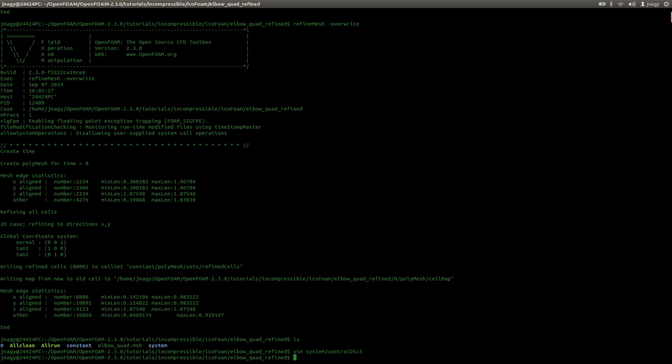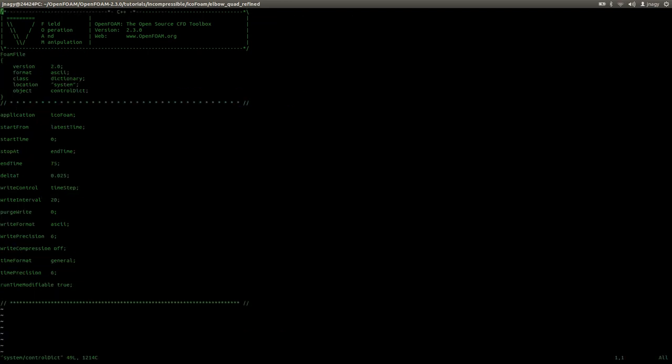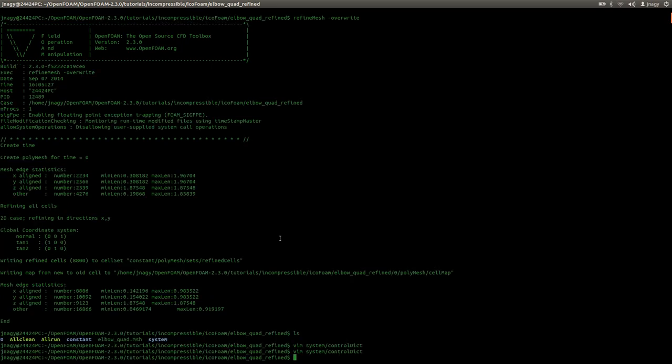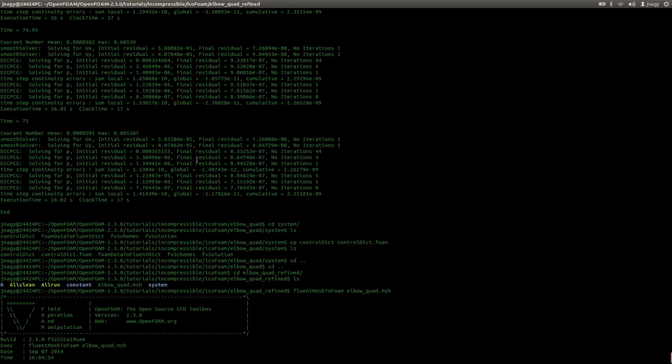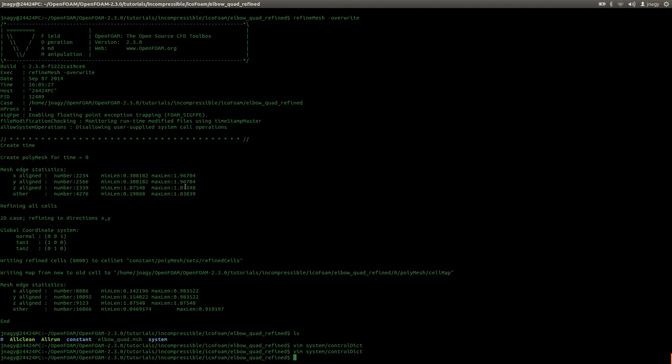And now if I open it up, now it's saved. Now the reason for the smaller time step is actually this Courant number, because in the Courant number you have your time steps, and by decreasing the length of your cell you have to change also your delta t, but I will come to that in a later tutorial. Just believe me that I have to do this.